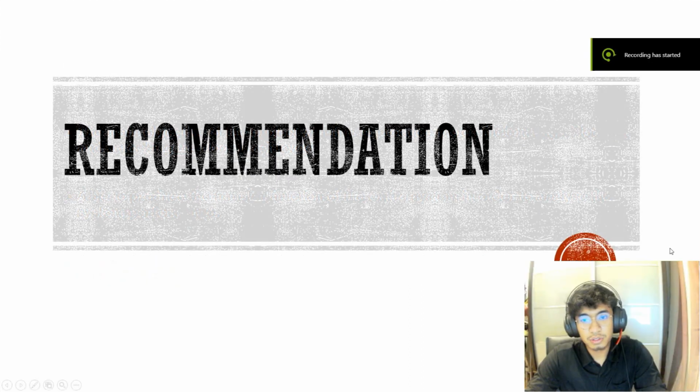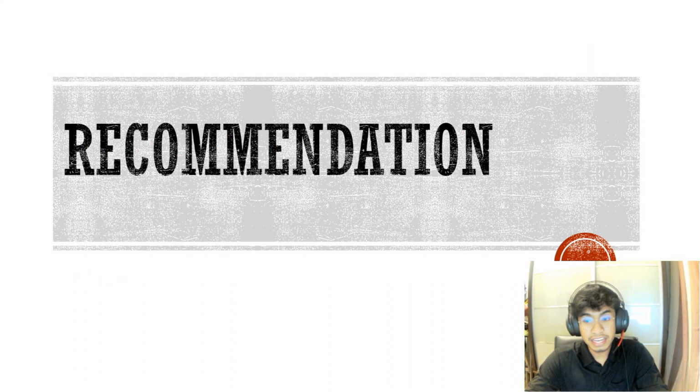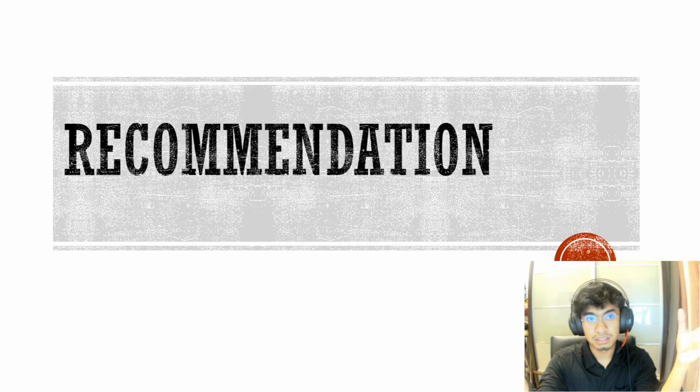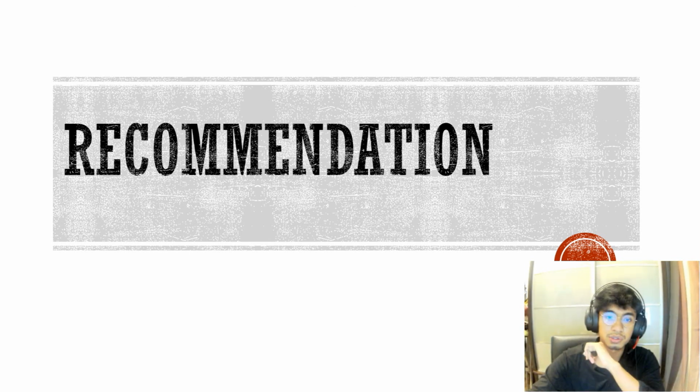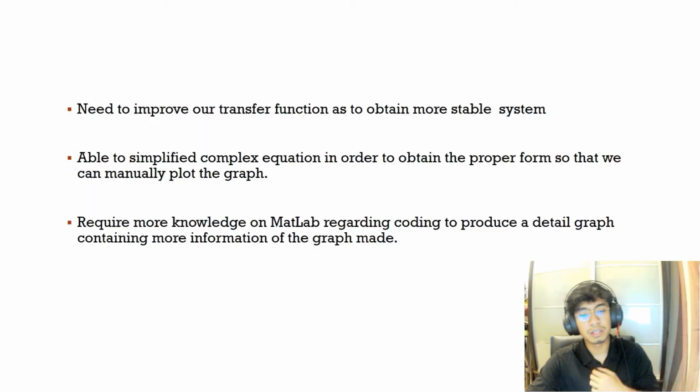Okay, now we have come to the very last subtopic for this project, which is the recommendation that we would like to suggest to improve the findings of our project. There will be 3 recommendations that we can do to improve our result. First, we need to improve our transfer function to obtain a more stable system. As we can see before, we got the root locus, which is not very stable because it is located on the right side of the S-plane.